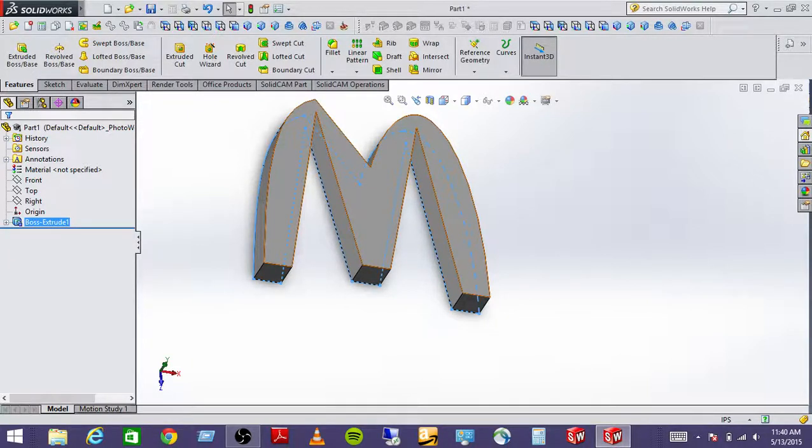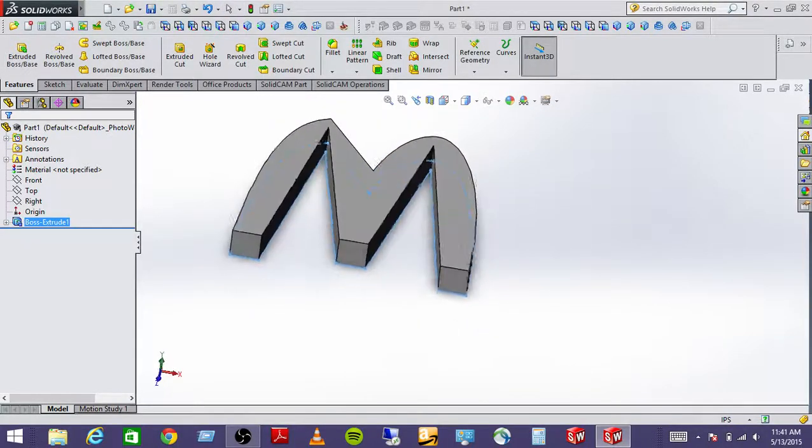Because material comes in what we call nominal sizes, which is approximately a 1/4 inch. It's close, but it's not exact. And you guys are going to be pretty good engineers once you leave CU. You're going to be doing some things that are more accurate than the material that comes in. So you need to understand that materials come in nominal sizes, and you either need to find out the nominal size and enter that into your CAD models, or you need to allow for a tolerance that's big enough to accept those nominal deviations in those nominal sizes.